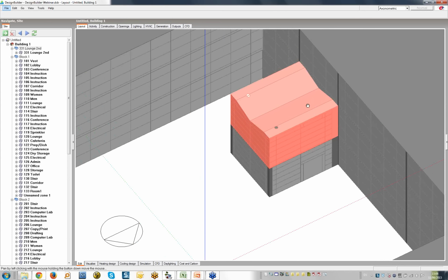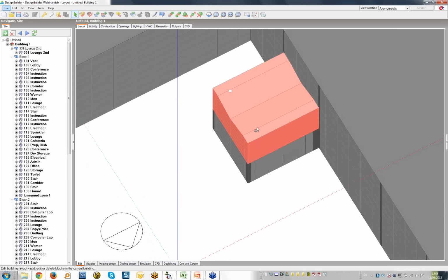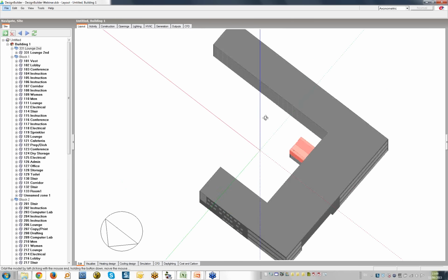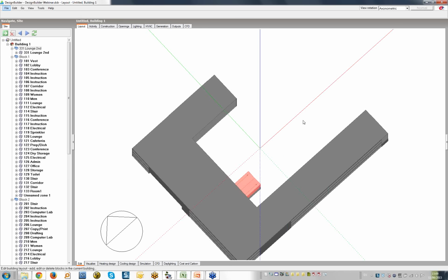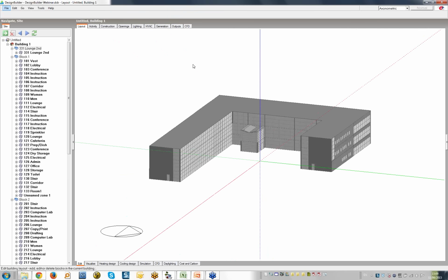Where you can clearly see the holes in surfaces imported from the BIM model. These would not be a problem for EnergyPlus simulations, but this block would require repair for daylighting and CFD calculations. Orbiting the building, you can see the geometry for all surfaces with no gaps.